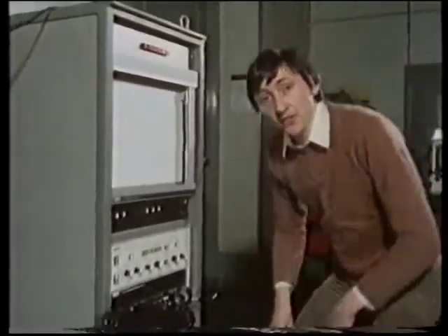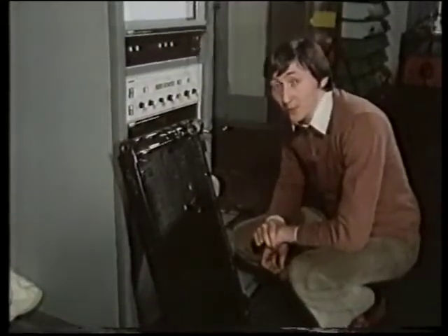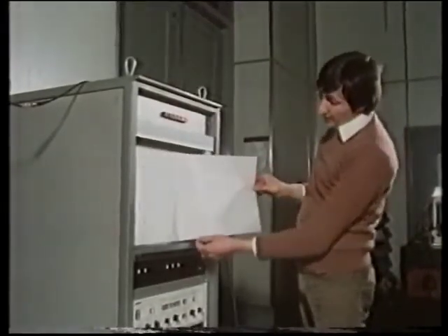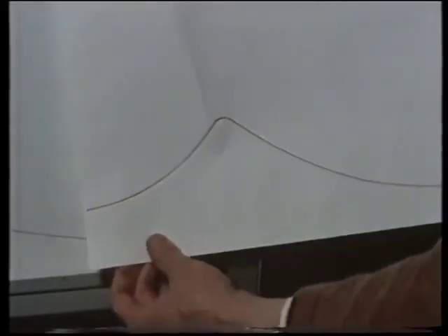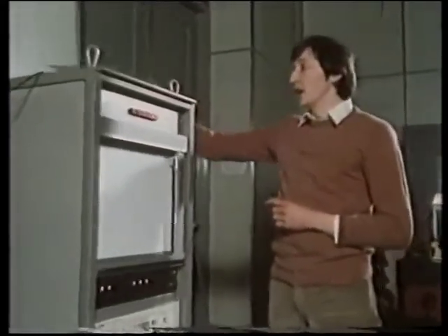What they decided to do was to increase the damping. And they did that by clamping the honeycomb much more firmly between the top and bottom plates. And this design of radiator may not look very different, but let's look at the transmissibility. That sharp peak has been greatly smoothed out. Less amplitude of vibration, less stress on the honeycomb, and the new design has got a life which is over 5 times the original. So that's not a bad return for the investment of a little bit of vibration theory.